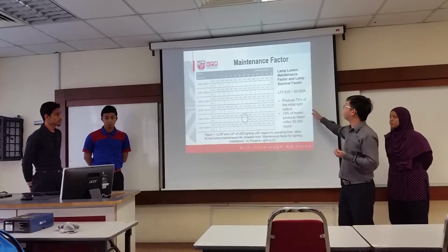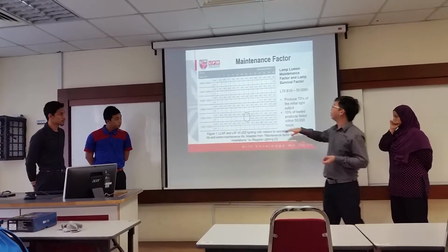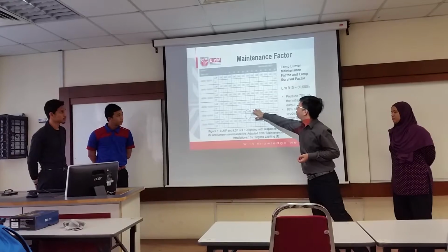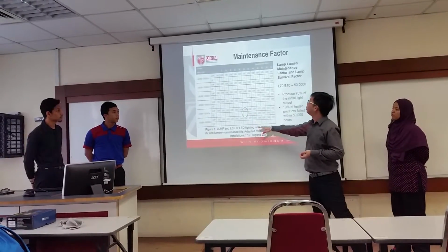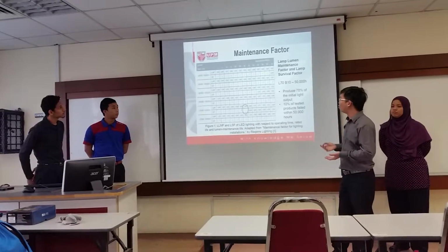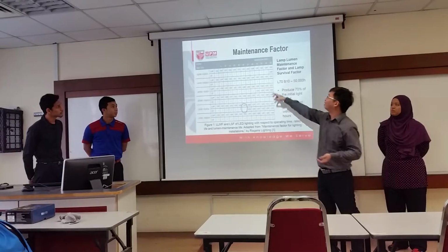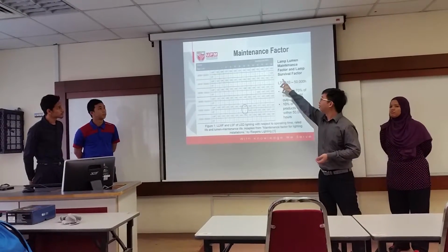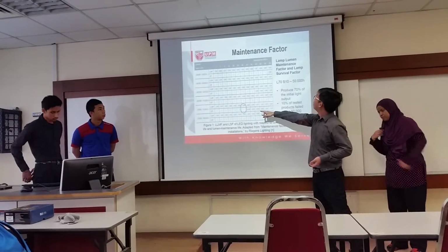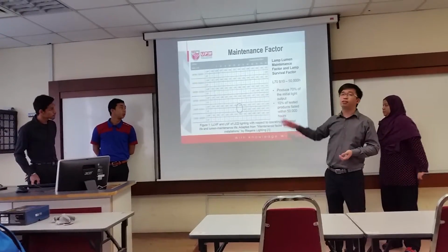So based on this rating, we managed to find the maintenance factor from the table. The expected operating hours for this luminaire in this library is 30,000 hours. So we can find that the lamp luminance maintenance factor is 0.84 and the lamp survival factor is 1.